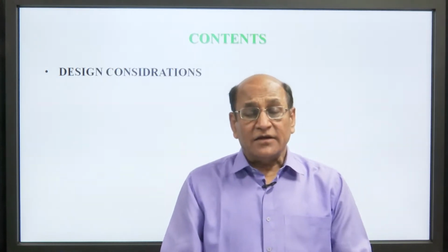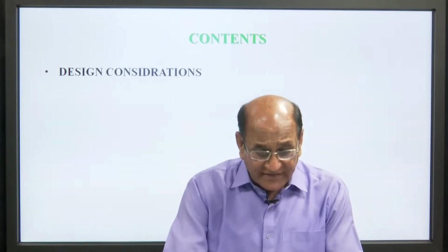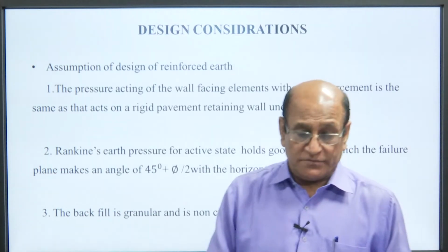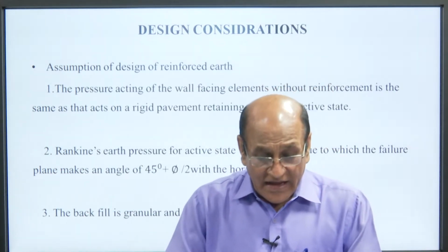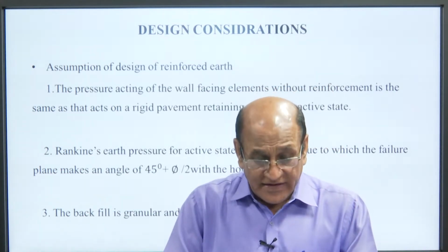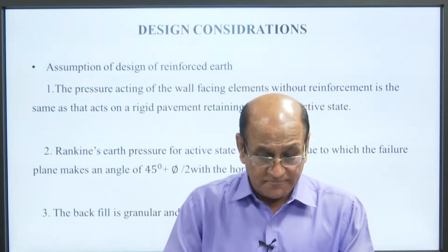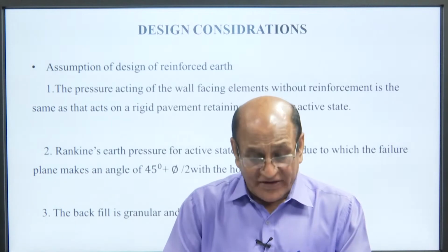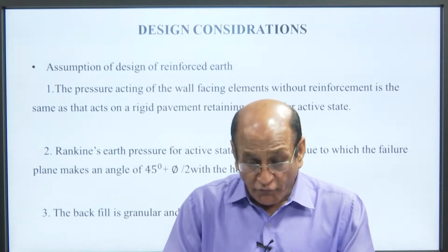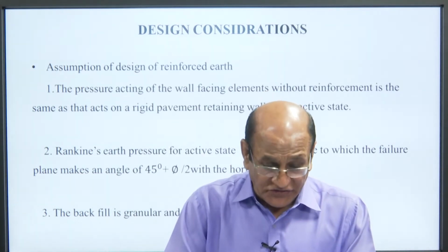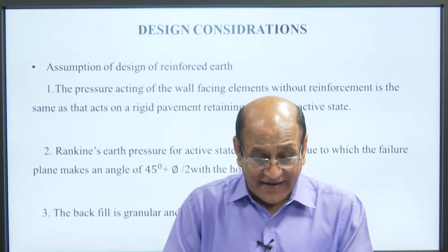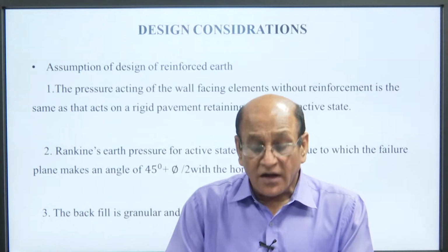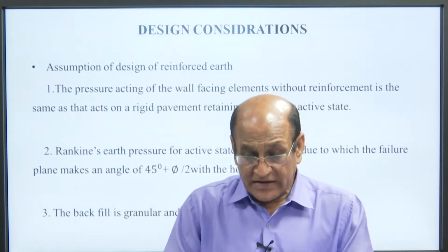The contents today I will take up design consideration. So, design consideration, there are assumptions of design of reinforced earth. The pressure acting on the wall facing element without reinforcement is the same as that acting on a rigid retaining wall under the active state.